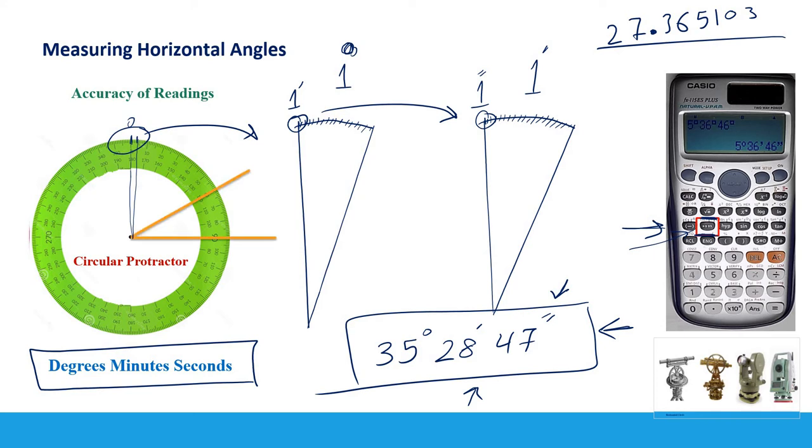And guys, because in surveying we are usually working to a very high level of accuracy, instead of measuring this angle from one direction, for example from left to right, and then saying it is 30 degrees, 1 minute and 2 seconds, we are going to measure it from left to right and then from right to left, and then take the average.